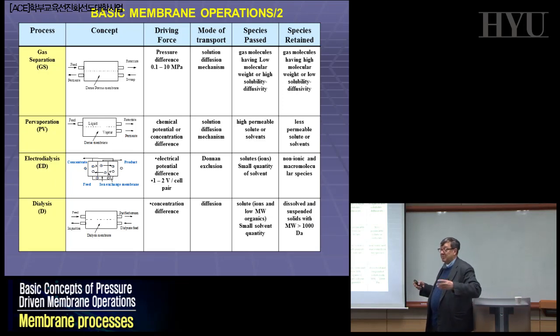You can do the experiment without the membranes. You can make a piece of polymer in your beaker and, changing the kind of solvent, you measure adsorption and desorption, and you will realize if your material is appropriate or not to make a separation, depending not on the morphology of the membranes, as in microfiltration, but only on the adsorption and desorption phenomena.